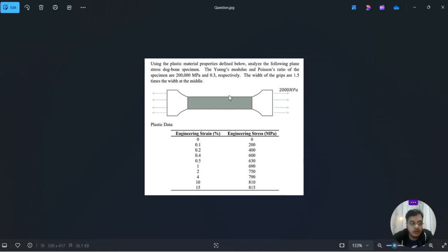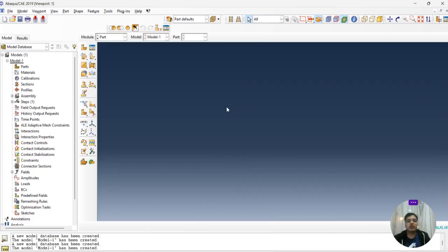Here we will also learn not only about defining the plastic strain, but also to understand how Abaqus in general works. If our analysis gets aborted, it does not always mean it is due to some error. Sometimes it means the defined properties or the maximum peak values are already reached. That's what we will see here quickly.